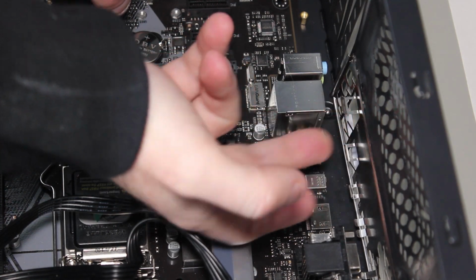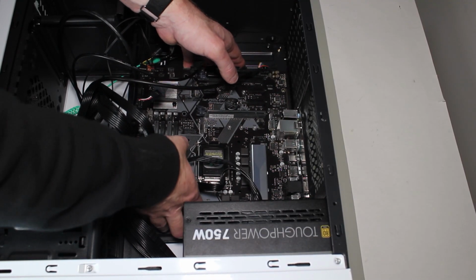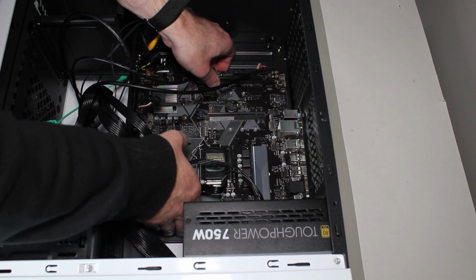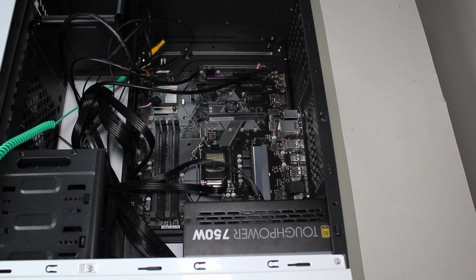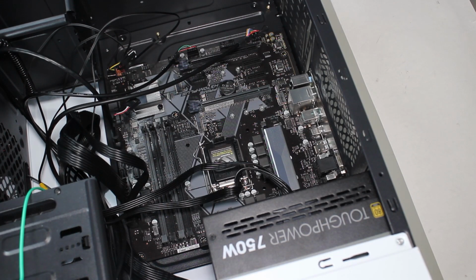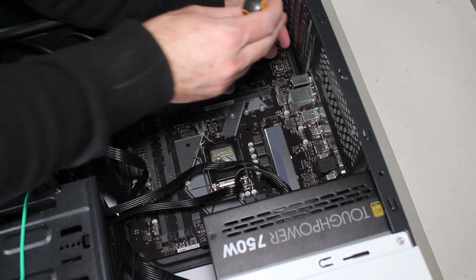I will attempt to put the motherboard in again, with a small angle downward to get under the clips of the I/O shield. It can be difficult to get the motherboard in with the clips on the I/O shield. However, if you force it, this risks bending the clips downward, which can block the connector. If you have trouble putting the motherboard in, bend some of the clips upward just a little bit and try again. You don't want to bend them up too far, as this will affect how it will seal the connector. But if you tilt the motherboard when installing it, this helps get under the clips and helps you put the motherboard into place.